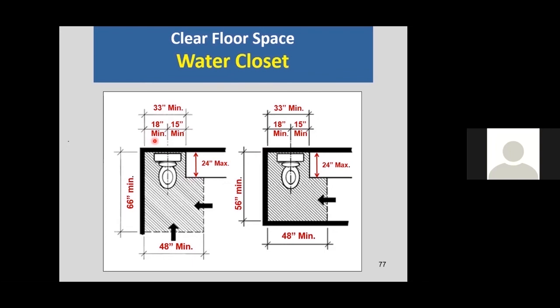But if we're looking at the ANSI standard, and that's what we'll be looking at in Michigan, especially for new construction, now this is the 16 to 18 range for a remaining clearance of 33 inches behind the toilet if we've put in this overlap for 24 inches max. So the primary difference here is we're no longer looking at a very problematic absolute dimension in the field of 18 inches, but to a more workable range of 16 to 18 for the toilet location.